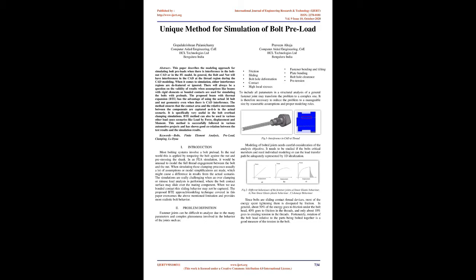The simulations are really challenging when an overclamping or misuse load analysis is performed, where the bolt contact surface may slide over the mating component. When we use bonded contact this sliding behavior may not be captured. The proposed BTE approach/modeling technique covered in this paper overcomes the above-mentioned limitation and provides more realistic bolt behavior.